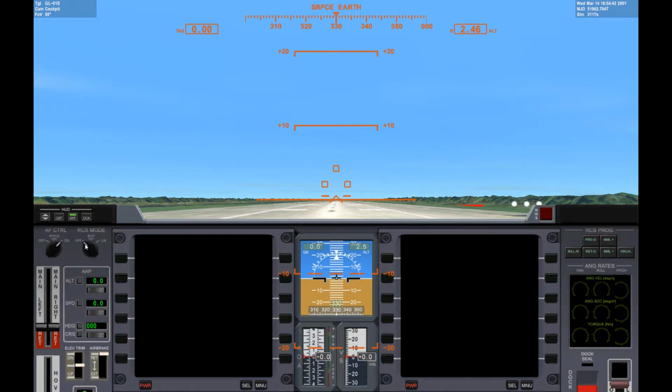Rotation. Attitude off. So we're going to turn that off so that I don't fire the jets. That's what you don't want fired. You can program the RCS, and these are your information here. So you can run these autopilots. I'm not going to explain how they work, but the most important one is kill rotation. If you're spinning, and there's no airstream obviously in space to stop your rotation, kill rotation is an autopilot which will null your rates. It will stop your rotation so that you're not moving fixed to some object.